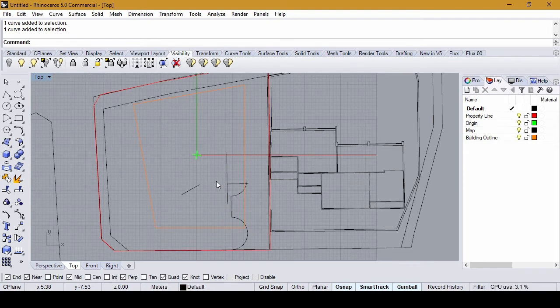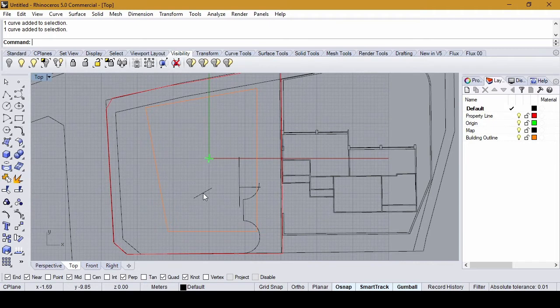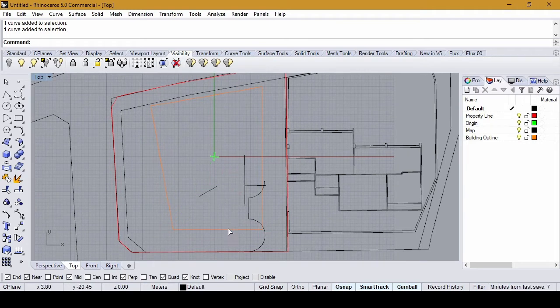So now the east facade and the south facade of our site is completely aligned with the Y and X axis. The reasons for doing this are obvious to me, maybe not to you, but any CAD and BIM software that works in coordinates, a line going from 0 and along the X axis is going to be mathematically much easier to describe than a line going like this line, for instance. So this line is easier to calculate than this line. Alright. I don't know if I can try and explain it in a simpler way. So this is the basic setup that we want to have.